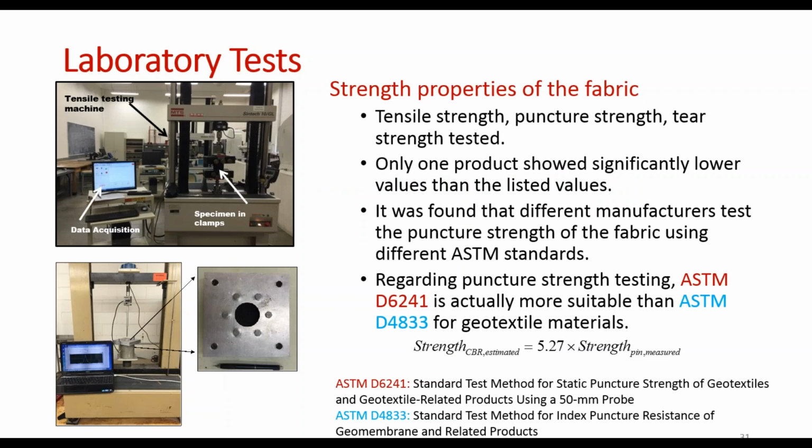And the strength properties of the fabric, including the tensile strength, puncture strength, and the tear strength. All of these three strengths were tested, and only one product shows slightly lower values than the listed values, which is good. And it was found that different manufacturers determine the puncture strength of the fabric using different standards. And we studied the different standards, and